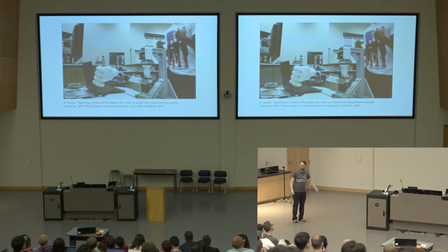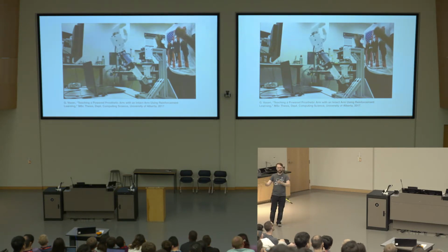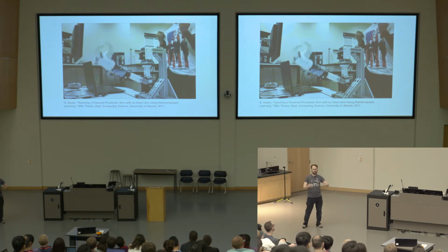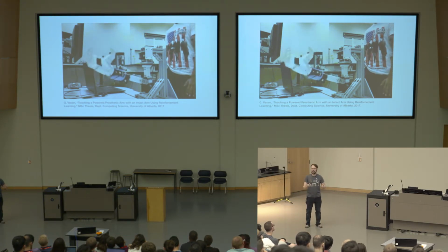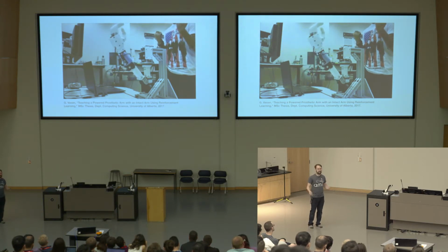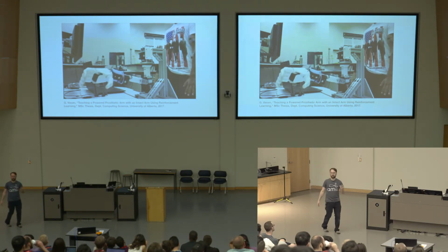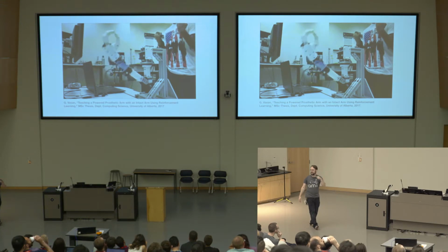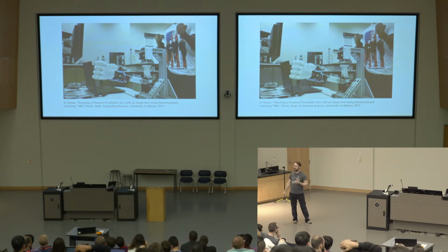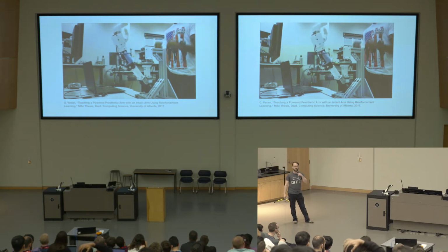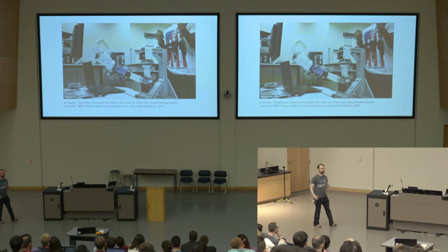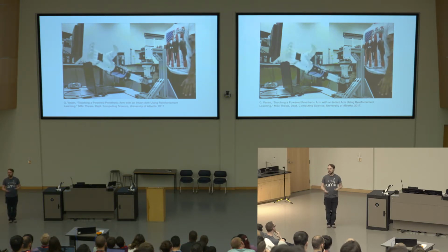There's actor-critic control learning. In that study I showed you earlier, where I told Osmar that we broke the robot, we also looked at using generalized value function predictions learned in real time as the only input to, say, a policy gradient learner, as input to a more complex control learning process. Predictions can adapt really quickly, in 5 or 10 minutes, to a new situation, but the control learner, through trial and error, takes much, much longer. So just putting in real-time learned predictions as predictive representations of state also has great utility.